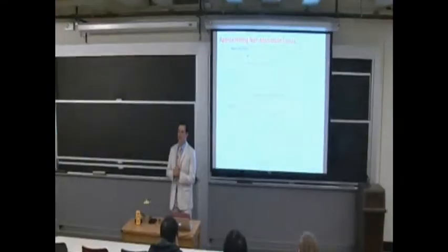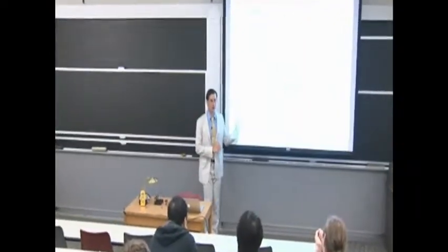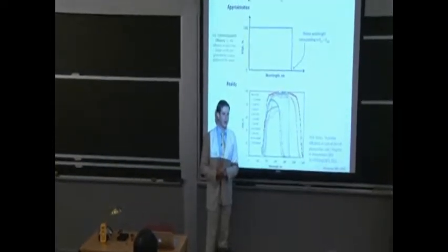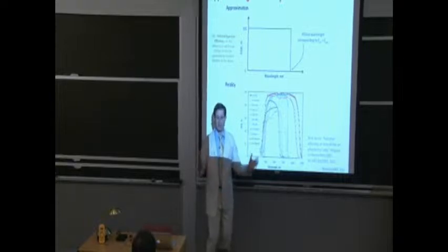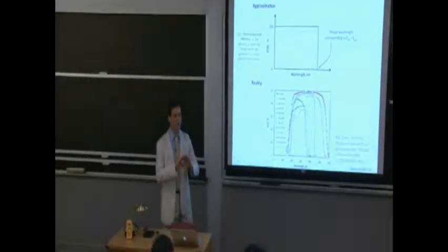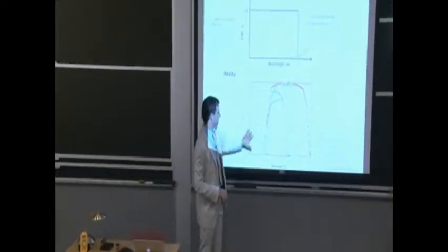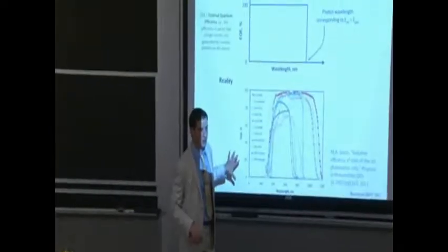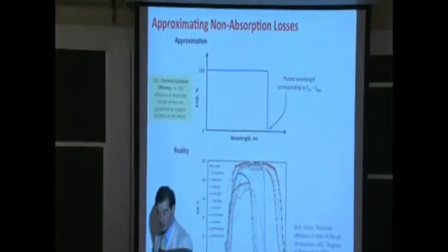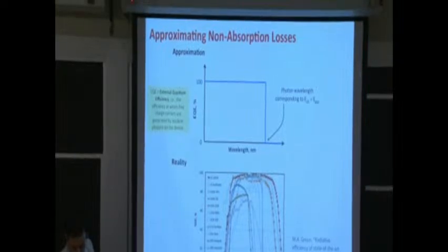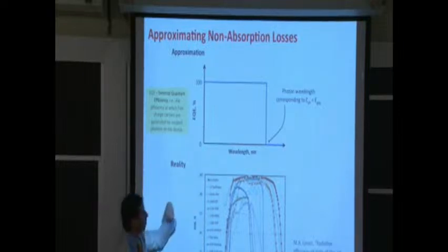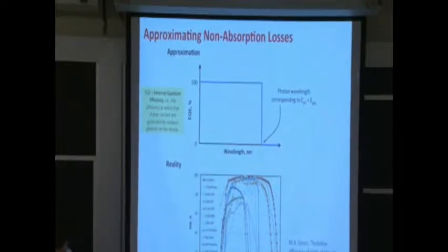But why don't we care? For the purposes of just this engineering approximation, why aren't we bothered by these photons that we're losing down there? The percentage of the solar spectrum that falls in that region is small. Absolutely. So what we're doing is an engineering approximation to get to a very first cursory efficiency calculation, neglecting things at the extremes: too short wavelength because there's just not a whole lot of solar flux down there, and too long wavelength because, again, not a whole lot of solar flux right there. So we're going to be using this approximation in our homeworks, and that will get us somewhat close.